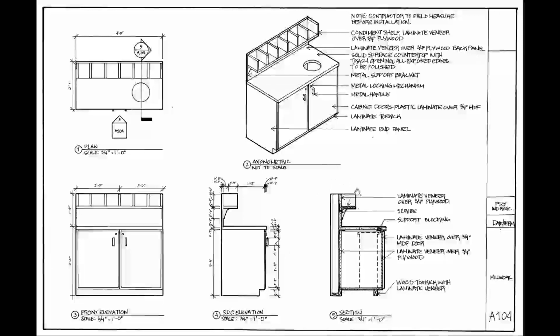But again, moving on here to the section, this is another example where I started with the thinnest line weight so that I could get the detail that I wanted. And then I was able to say, all right, I think I can go the next level up with the profile lines, a little bit thicker on some areas. But there are times with larger objects that I start with the profile line and go in decreasing line weight hierarchy. And there are other times that I start thin and then go up. The only way that you learn this is through experience.